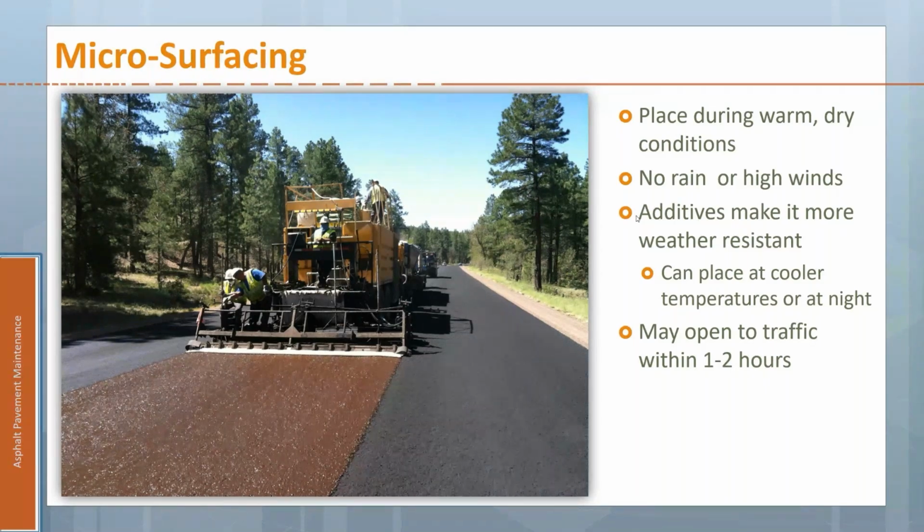And since we do have a little bit more structure to it than the traditional slurry seal, it might be something that you use on a location with a little higher traffic, in which case traffic control is a bigger issue, and sometimes night work is the easier way to go about that. So this is something that will allow you to do the project in the overnight hours. And then with those additional polymers and the quick setting product, you can get this back open to traffic within about an hour or two.